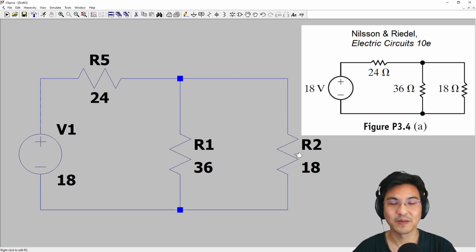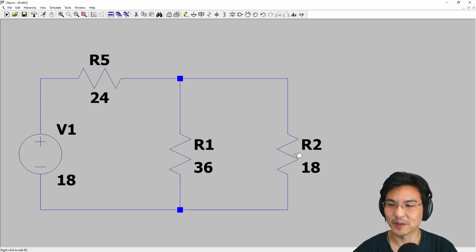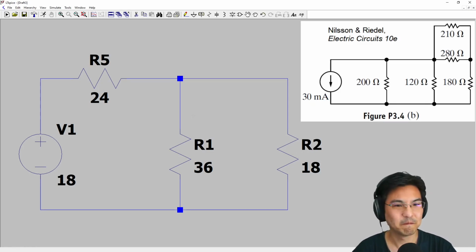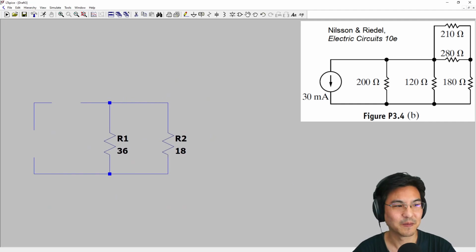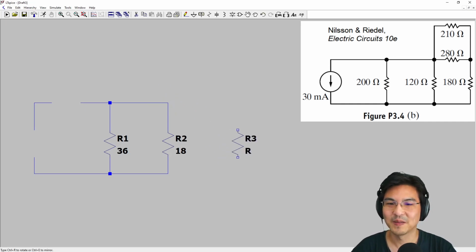All right. Let's try out a different schematic. How about this one? Okay, I'll just recycle some of this. I'll cut some of these parts out of here, and then I'll add to it. Okay, so I need 3 more resistors. I'll press R, put one here, and I'll rotate this, put that here, and then here.